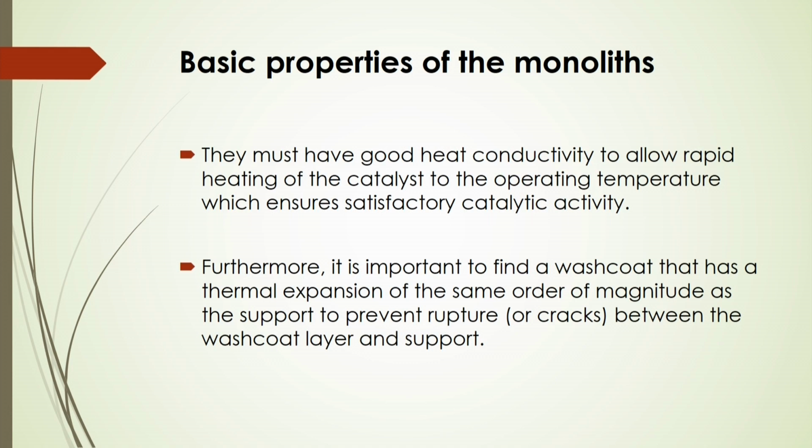Also you have to remember that it may be worth finding a wash coat that has a thermal expansion of the same order of magnitude as the support, to prevent ruptures or cracks between the wash coat layer and the support. That is why you have to consider the temperature tolerance of the material you are considering for designing that monolithic structure.